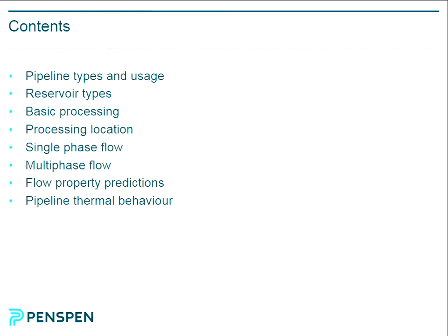So, single-phase flow. Effectively, the analysis of multi-phase flow is an extension of our understanding of single-phase flow. Very important in any kind of analysis related to hydraulics and flow is how you predict the properties: things like density, viscosity, surface tension, and volume fraction, how much gas and how much oil is present at any particular temperature and pressure.